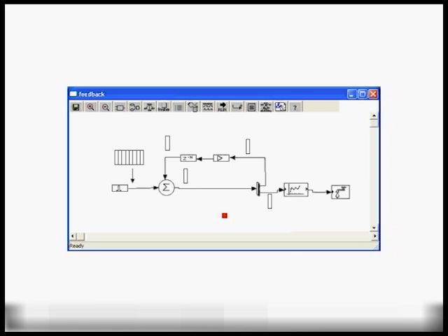So let's reflect on that. In many simulation situations, you're not building the simulation based on primitive blocks, but in fact, blocks do a lot of processing. For example, it does an FFT, or it does a convolution, and so forth. And in this case, if you process a sample at a time or multiple samples at a time, it doesn't make that big a difference, except in cases where you're building your simulation up with a lot of primitive blocks. So we've actually done some simulations. We found out that even if we insert a block here and buffer up a lot of samples so that the rest of the pipeline is operating on multiple samples at a time on each call basis, there's not that much of a difference.